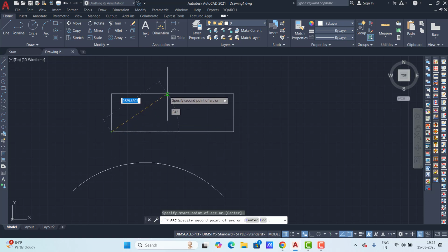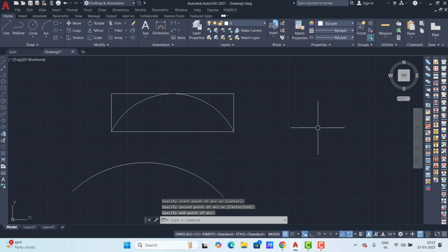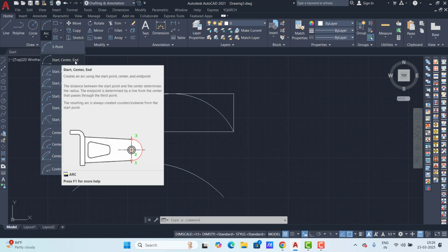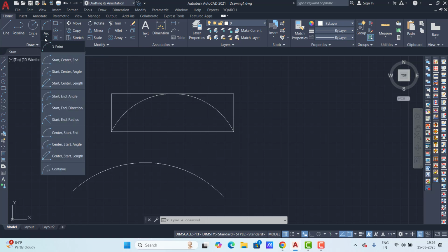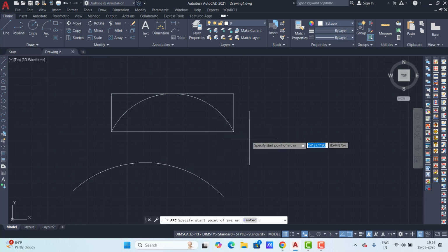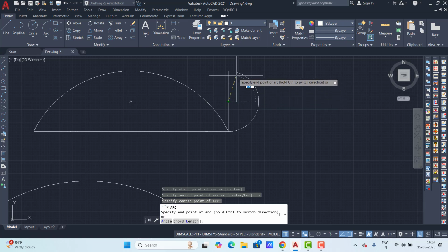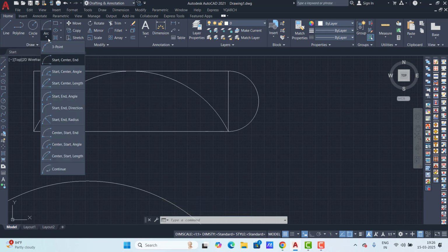Same, I want to make here. Give the start point here, give the center here, and type that one here. Suppose you type 1000, that is 1000. To check, go to dimension, draw dimension, take the arc length option here, and click this. You see, exactly this is not coming. So we press D enter, dimension style, edit, modify, text. Here we type 5, set current. Close.